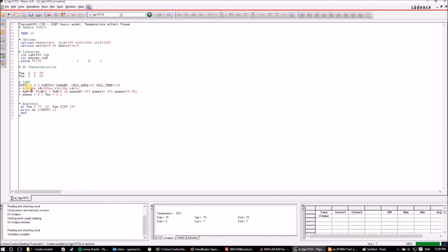We can now do the second part, and add the parameters we want to estimate. We do so simply by replacing any parameter we want to estimate by the command var_param followed by the number of the parameter in parentheses. So we'll begin with var_param(1), and we'll go until as many parameters as we want to estimate.